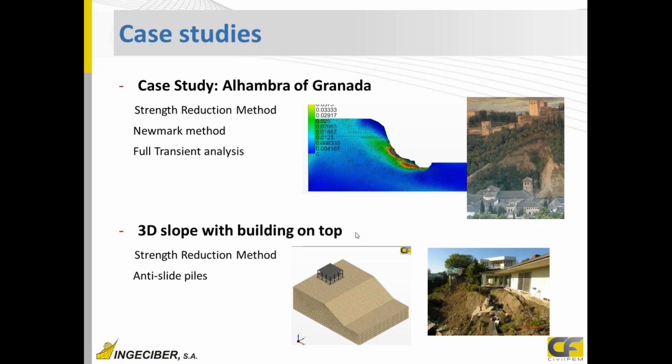Here you can add anything to the model, any sort of loads, any sort of way to model faults in the terrain with contact elements. Anything can be added to the model, and then you solve it, reducing the material properties and obtaining the safety factors. So this is much wider and has more widespread applications.